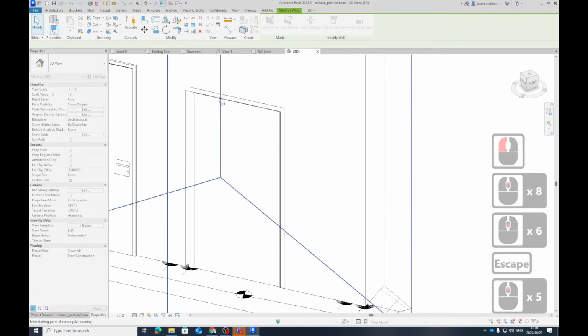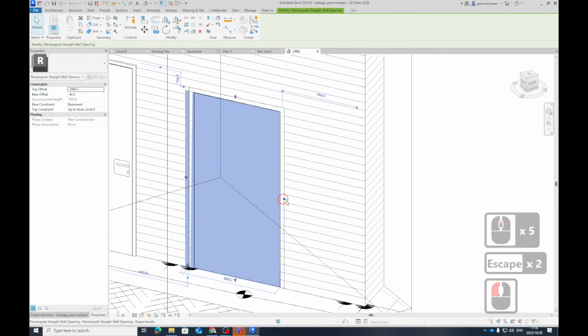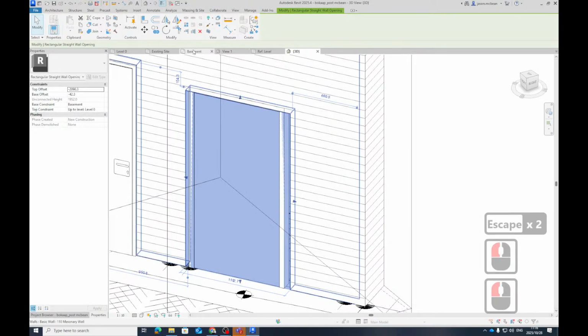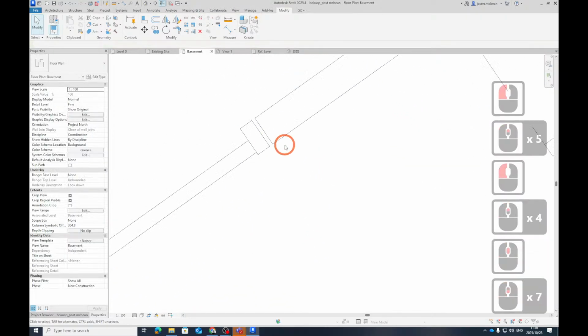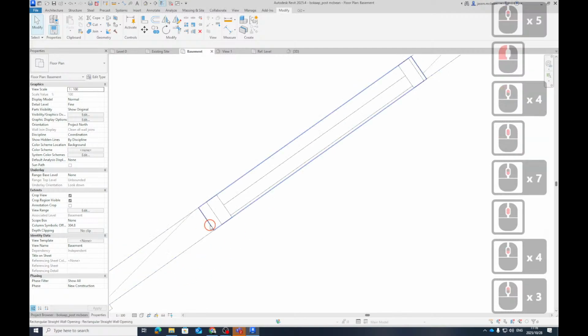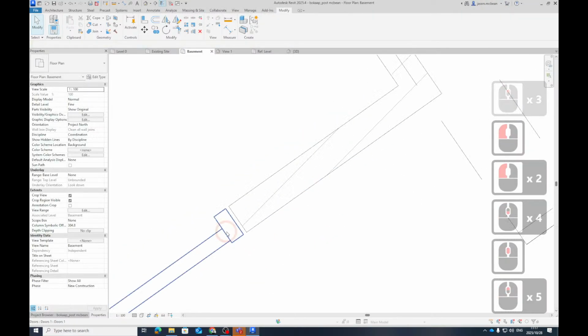If you need to adjust the opening, it's very easy to go and adjust the opening on plan. You can adjust this now on plan. I'll explain once we go to basement. It gets easy now to adjust this to work with this door. Okay. You can use the align command. Maybe that line's not 100% straight, but you can get this quite accurate. Okay.